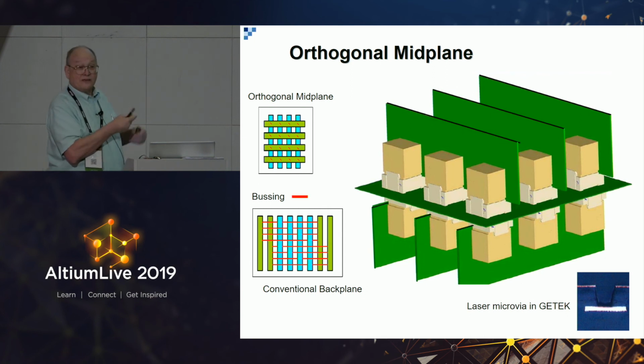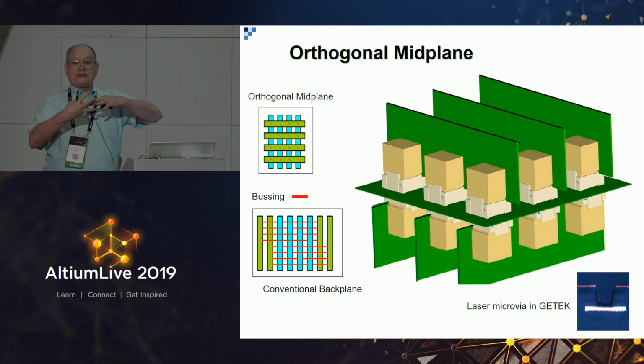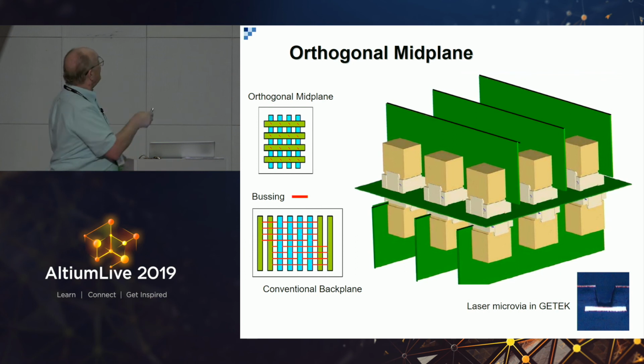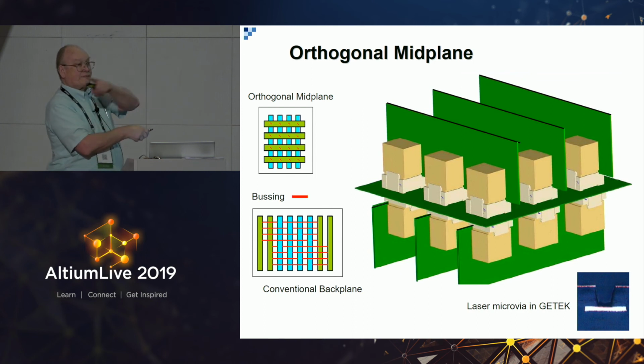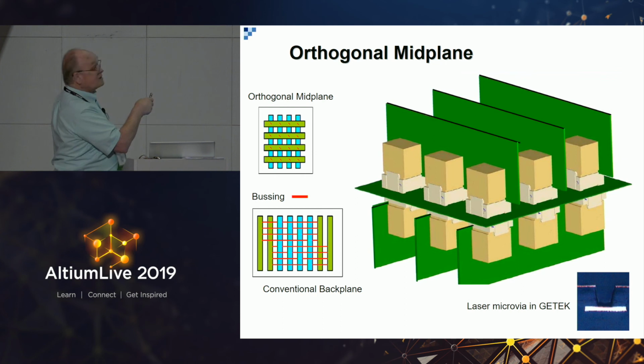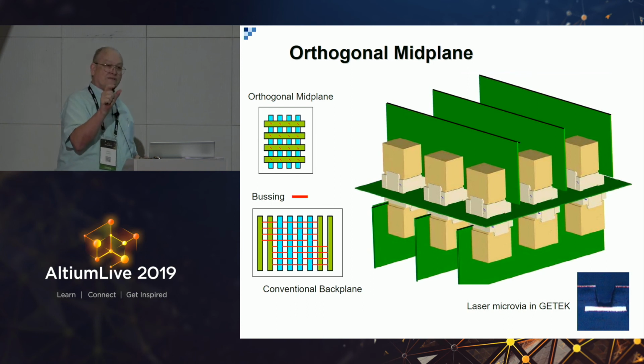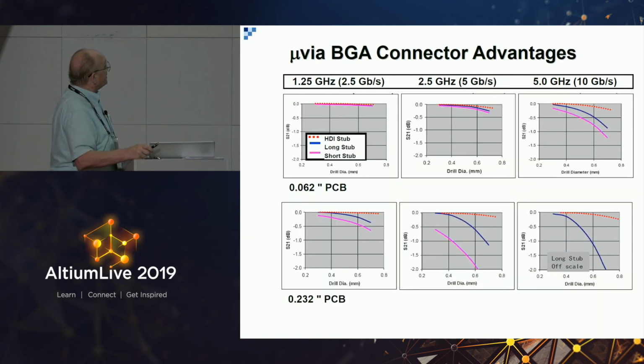So this is much more effective than a backplane because like this, the interconnect you see is very short. With a conventional backplane, we got long traces in the backplane running all over the place. With a midplane, we have very short connections between boards on one side and boards on the other side. And that's because of the 5G and the high frequencies involved here, we have to make all the critical traces as short as possible in those constructions.